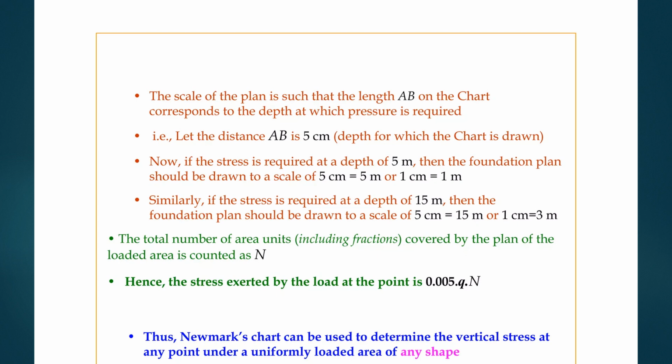The total number of area units covered by the plan of the loaded area is counted as n, and the stress exerted by the load at the point is 0.005 q n. Thus, Newmark's charts can be used to determine the vertical stress at any point under a uniformly loaded area of any shape.